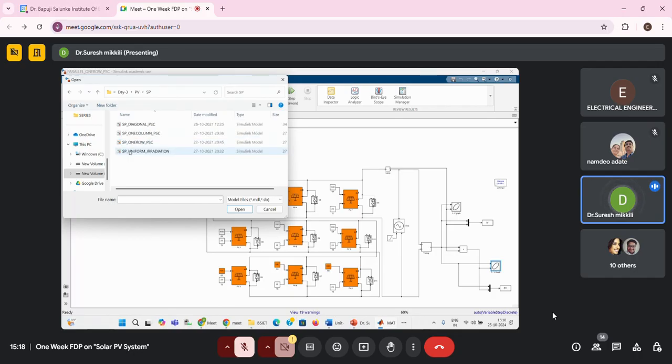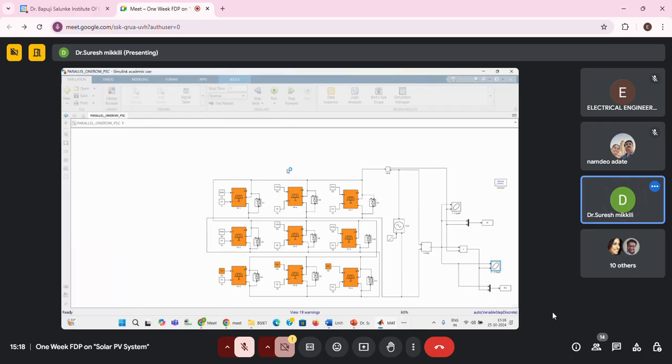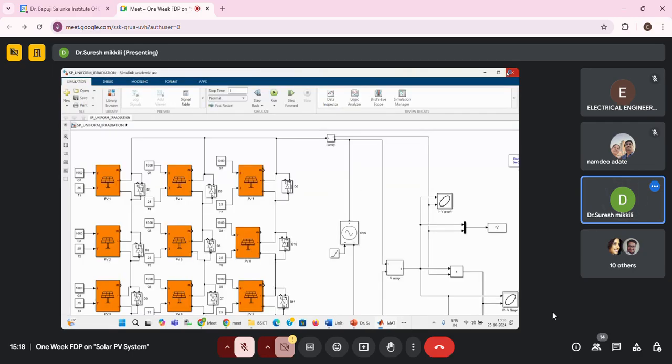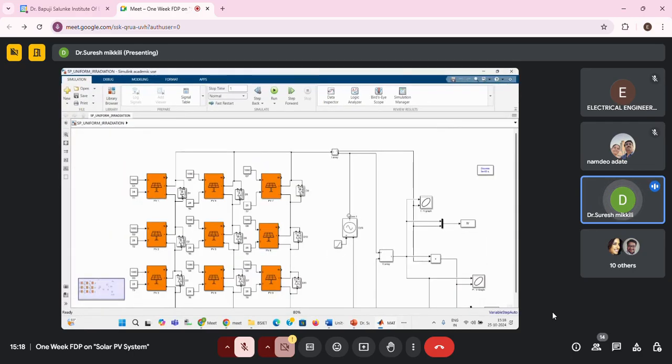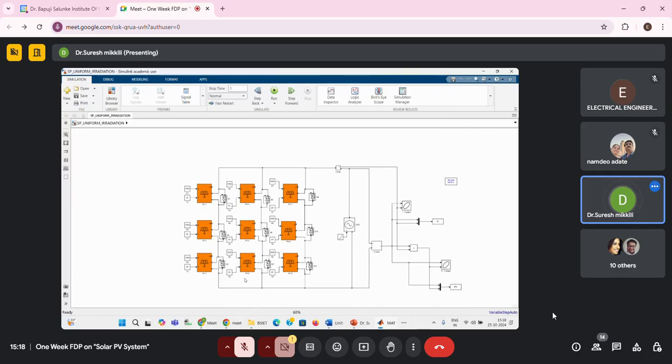So series parallel structure is similar to the series structure, but whereas the third one was connected to the fourth one previously, now in the series parallel structure, can you observe in the first column 1, 2, 3 will be connected, second string 3 more connected, fourth string, third string 3 more are connected. Now each string is connected in parallel. Do you observe this?